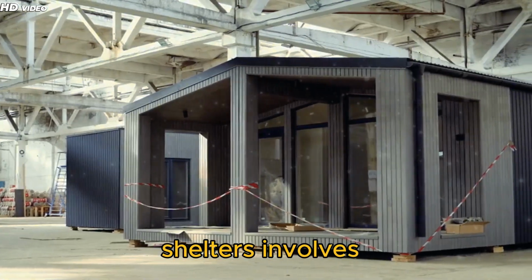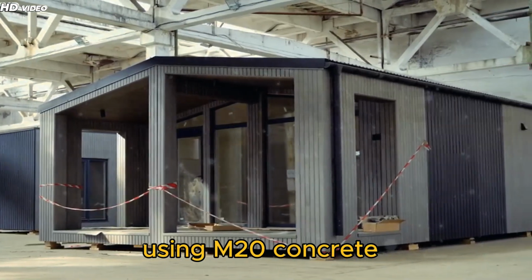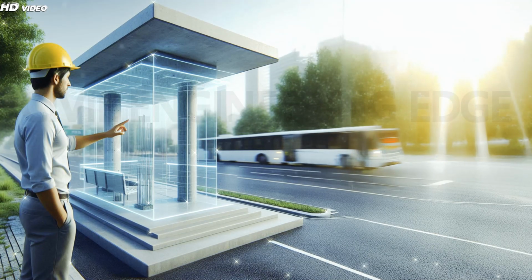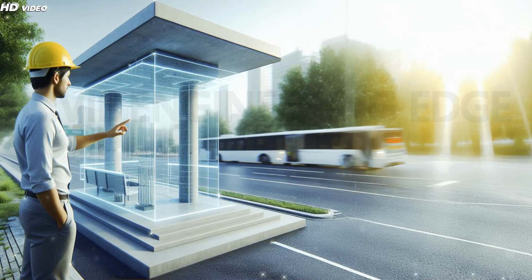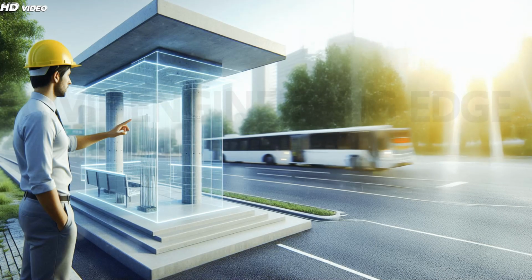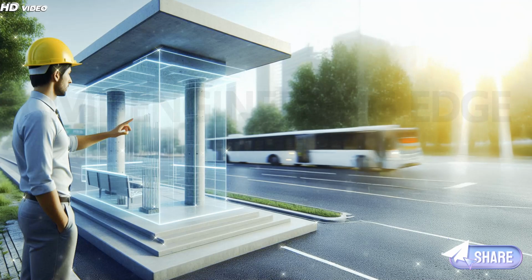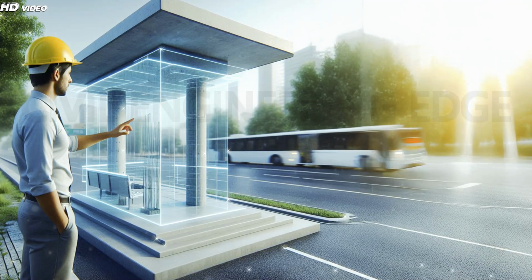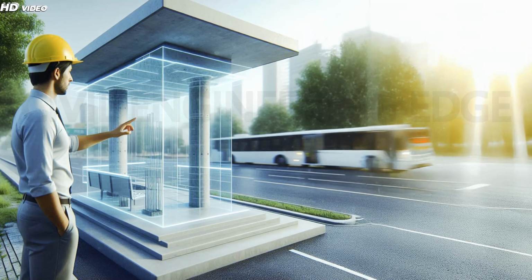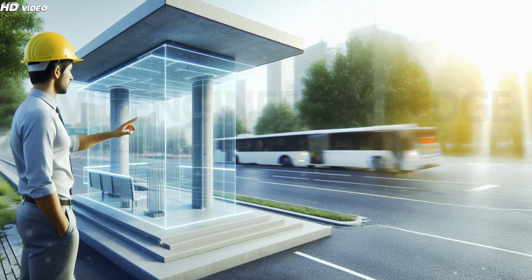Designing these shelters involves precision and structural detailing using M20 concrete and Fe415 steel to handle loads efficiently. The slab, usually 100 millimeters thick, is reinforced with main and distribution steel bars as per standards. The frame consists of a tapered beam, column, and footing carefully calculated to resist bending moments, shear forces, and foundation uplift. Why cantilever? It's modern, efficient, and visually elegant. No rear support is needed, reducing material and site congestion.